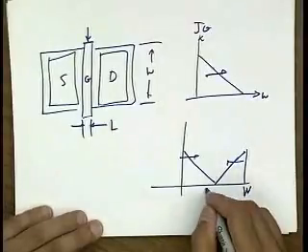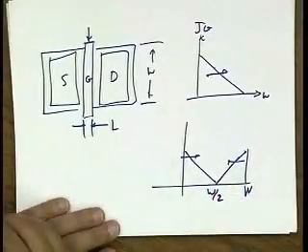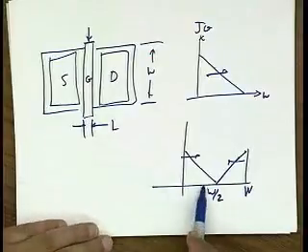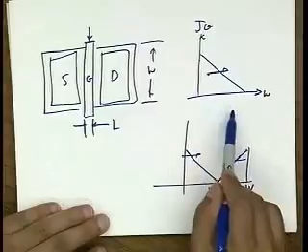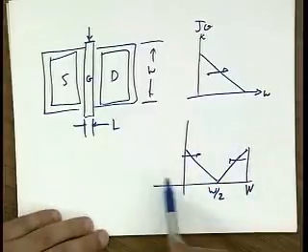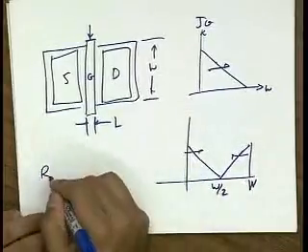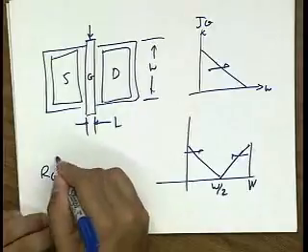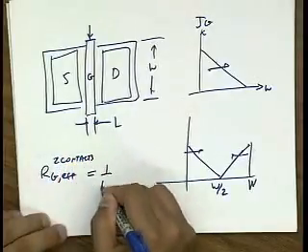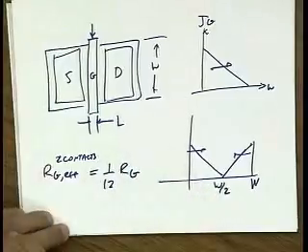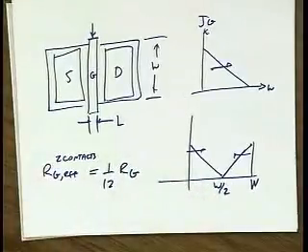So this is W again, this is W over 2. And if you do the math for this case, in fact you can apply this result. W goes in half, you have two resistors in parallel. You do the calculation, the effective gate resistance for two contacts is 1/12 the physical gate resistance. Okay?